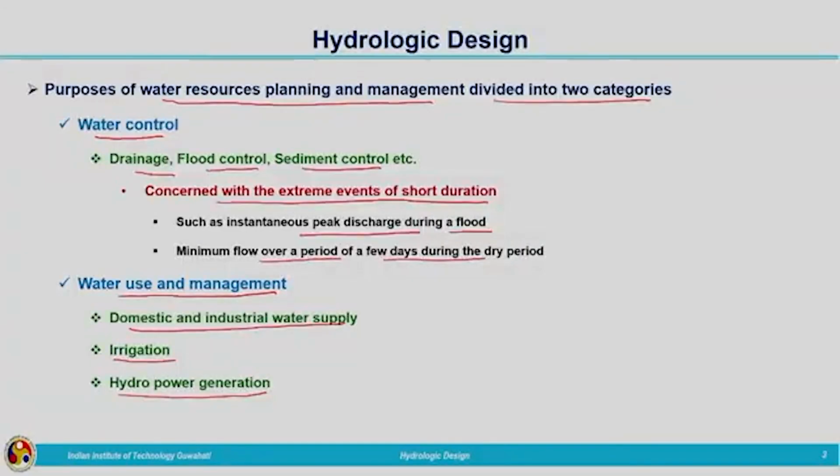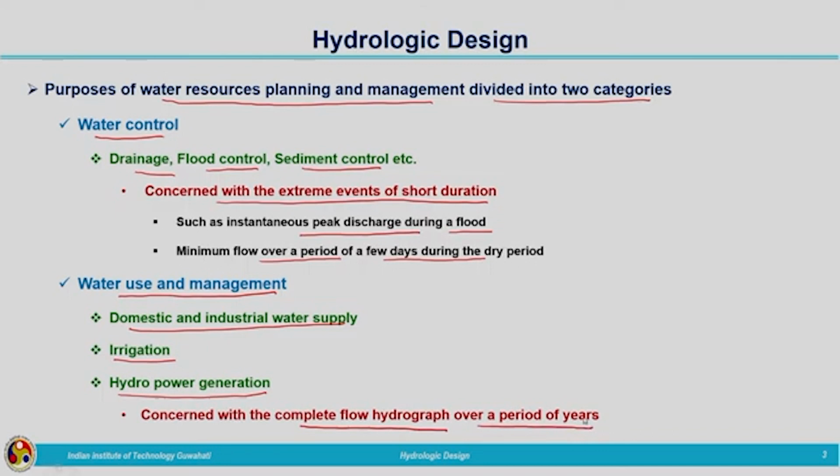And in the case of water use and management, we are concerned with the complete flow hydrograph over a period of years, because we need to provide water depending upon the demand. For that, we have to make use of the entire data over the years, and based on that the water supply, hydropower generation, all these things will be carried out.